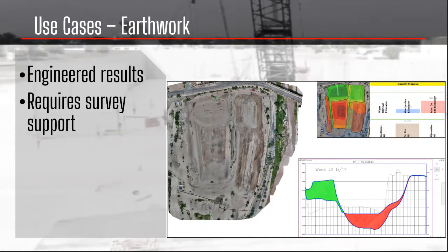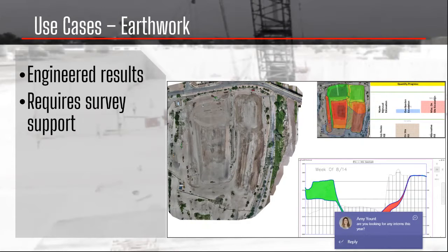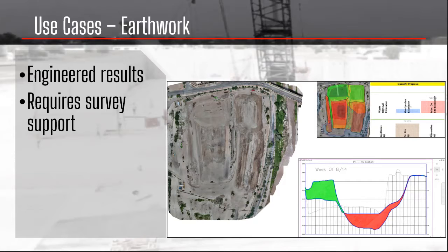And none of this would be really possible if we weren't using ground control points. And I feel like that's something that's going to be said, but needs to be stressed more, is using actual ground control points that have an accurate XYZ location tied to them, and then processing the drone map utilizing those.